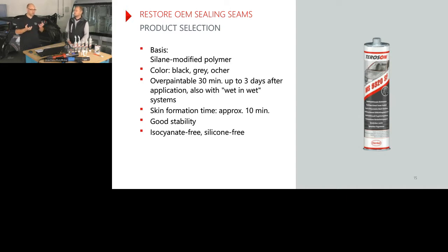This is good that the product can absorb more humidity to cure faster. Yes, and 30 minutes is not that much. So skin formation time is quite fast. It's 10 minutes. So in the first 10 minutes, it grabs a lot of humidity, and then it can be overpaintable. It has a good stability, so it stands like you apply it.